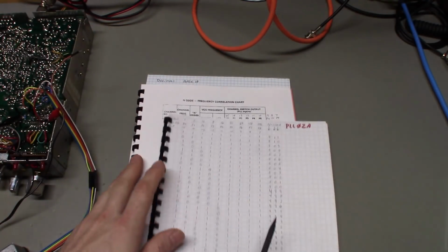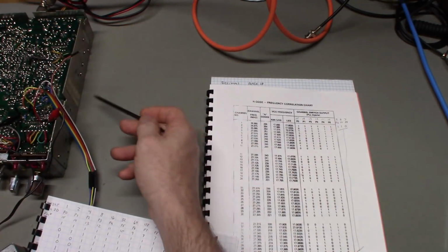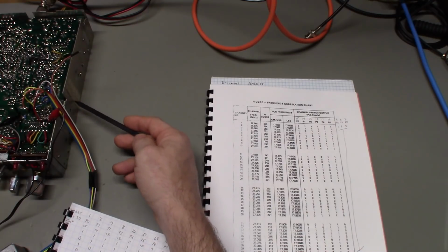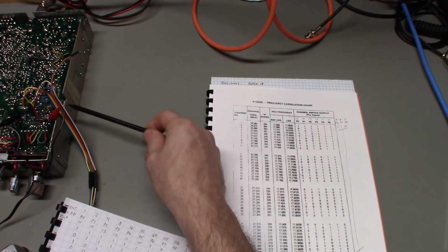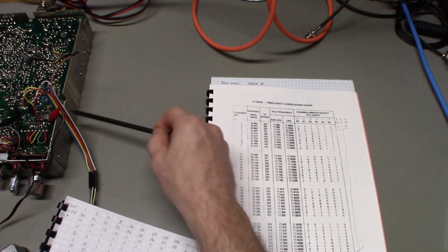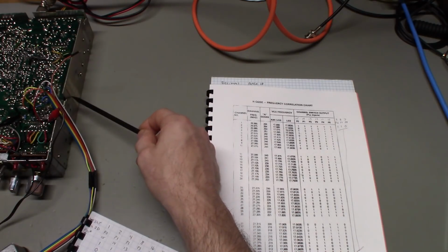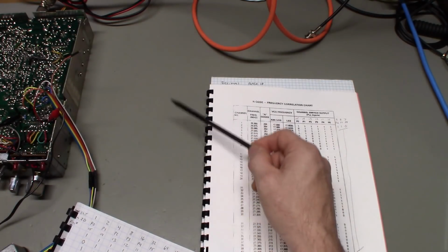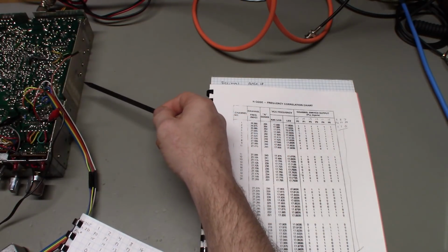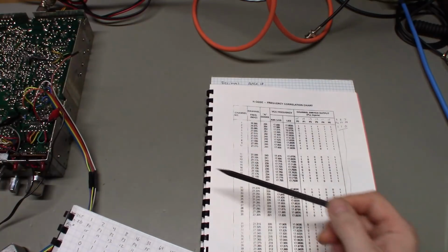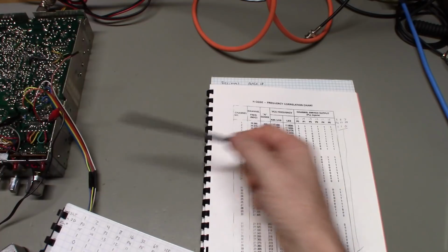And how can you find that if you don't have a service manual? There may not be. Actually, this radio here, honestly, there is no service manual for this. This service manual is actually for the base station version of this radio. It is a rare oddball radio. It's a DAC. But it's basically the same as what was used in the base station radio that had a vacuum tube driver and a final. This one, on the other hand, is a full solid state radio. It has a driver and final transistors. But I can use this truth chart, because the rest of the radio is still the same.